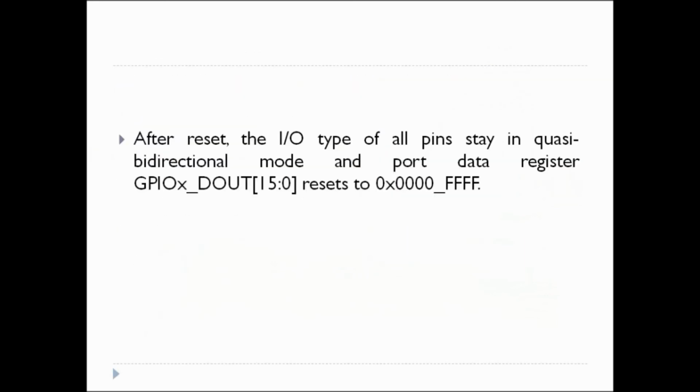So once you start writing code, if you want to configure the GPIO, the user has to use the control registers. They have to configure the control registers: which mode they want, or the value they want to drive, or if they want to read the value, what kind of register they have to access. The user has to be aware of all the control registers before programming the GPIO. Okay, that is one method.